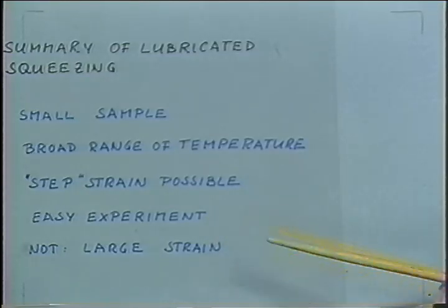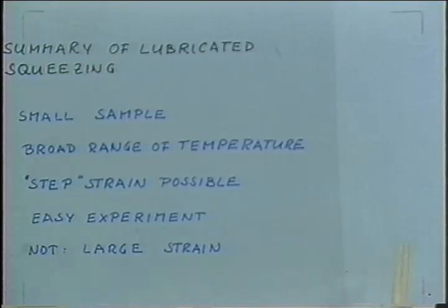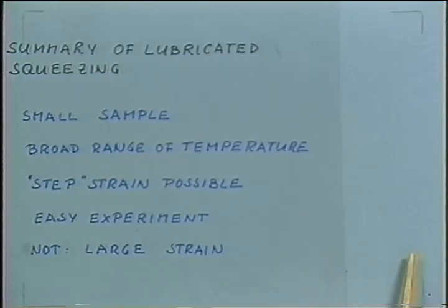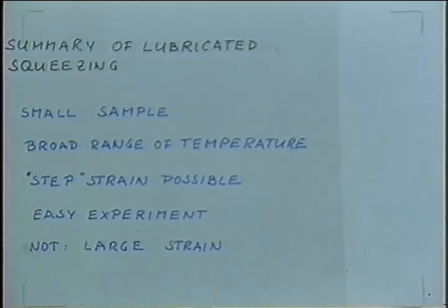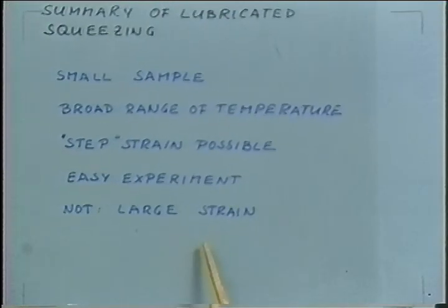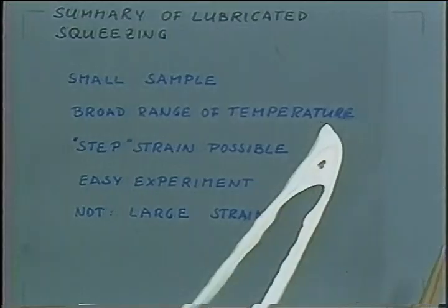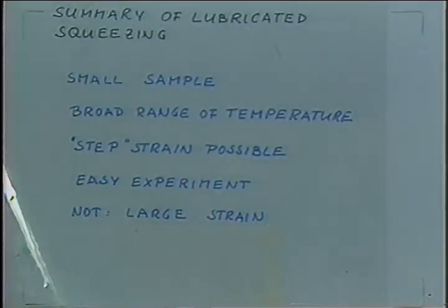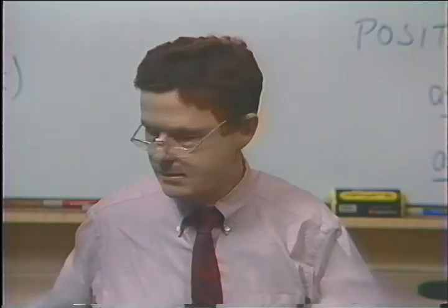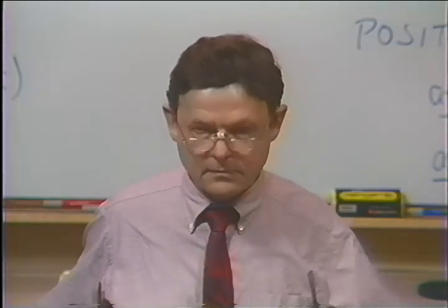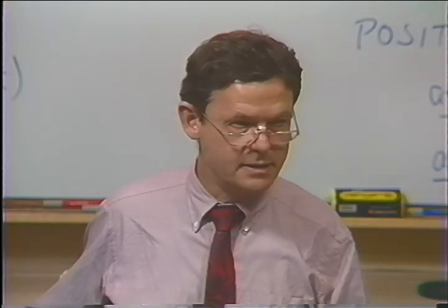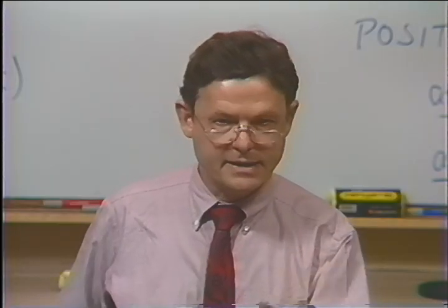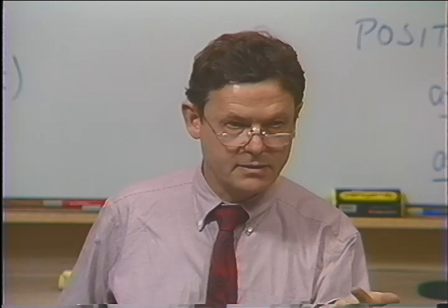Right? It's a beautiful experiment which Meissner built up, and he really can look at his sample. In fact, Zorsky also put glass plates in our squeezing apparatus and put marks in the sample, and then doing this lubricated squeezing, he also could look at the stretching and found also very homogeneous deformations there. Now the limitation of the lubricated squeezing is that the strain cannot be too large because you lose lubricant. You change the kinematics. So far about the batch experiments in uniaxial extension, in equibiaxial extension.